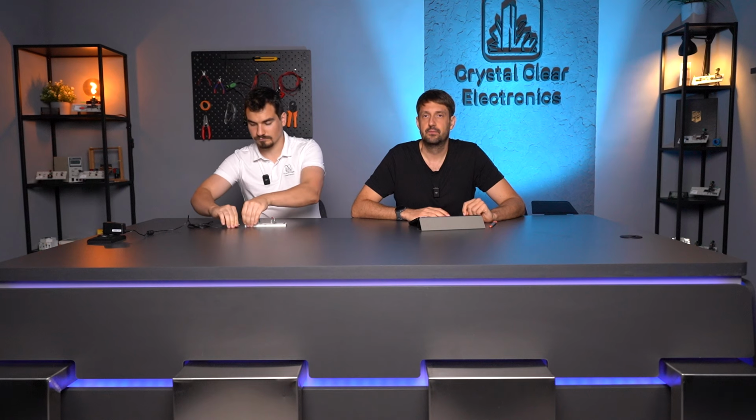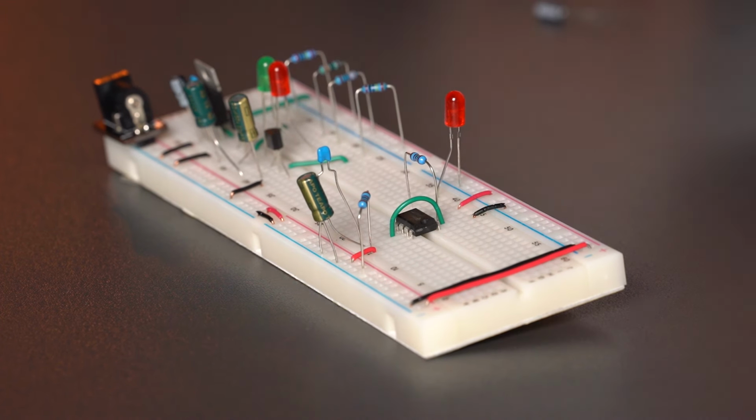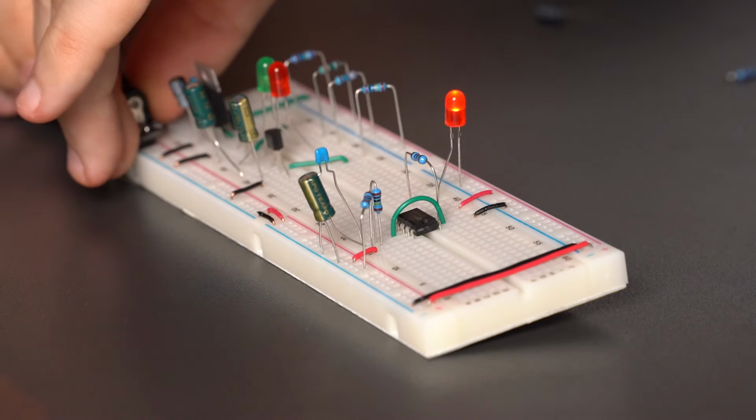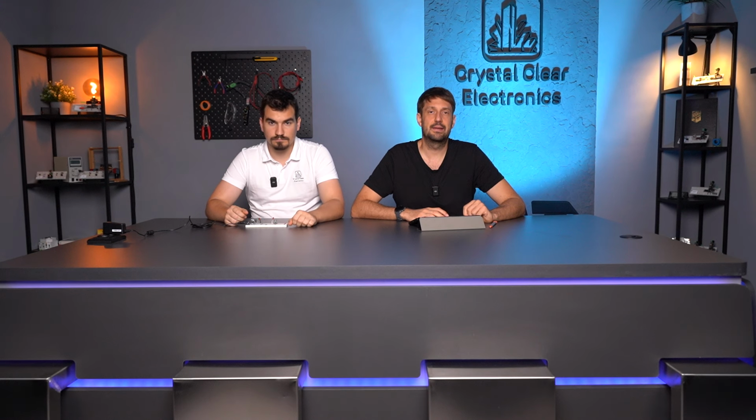Let's now replace R2 with the 1 megaohm resistance. This will increase the time of change in output. Use your multimeter to measure the voltage at the terminals of the C capacitor. You'll experience that while the LED is on, the voltage will increase from 4 to 8 volts, then the output will change, and the voltage will decrease until it reaches 4 volts, and then the process starts from the beginning. The two threshold voltages are exactly 2/3 and 1/3 of the supply voltage, so the circuit operates as described above.